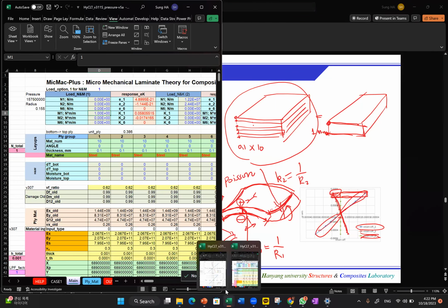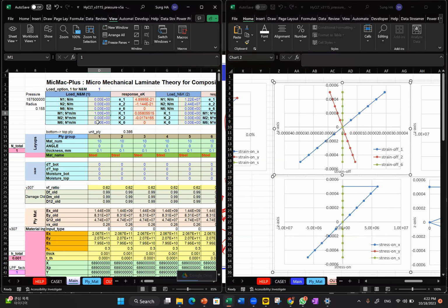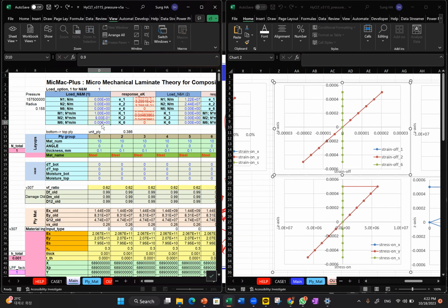Well, very easy and very straightforward. You just apply here 1. Then as you can see, all positive, in one direction and the second direction positive. There is overlap. I will just enter slightly different values so that you can see the difference. Same moment, same direction, and it shows positive, but if we apply one direction, please remember we will have an anticlastic curvature. So this is the important point.